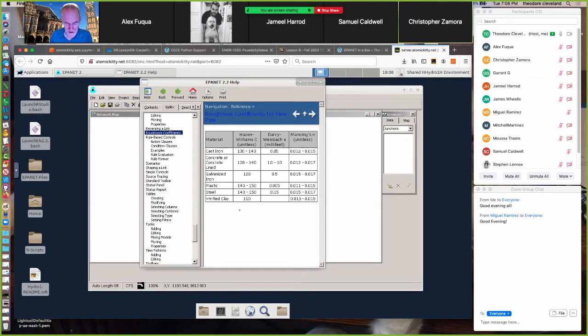So it has a little teeny table of roughness coefficients, and for cast iron, 0.85 and so forth. It's in weird units, but these are the actual numbers that you can enter into the program. So I'm going to copy that 0.85 because this first problem is a cast iron pipe that's joining the two reservoirs together. It's probably a dumb materials choice, but that's the problem.